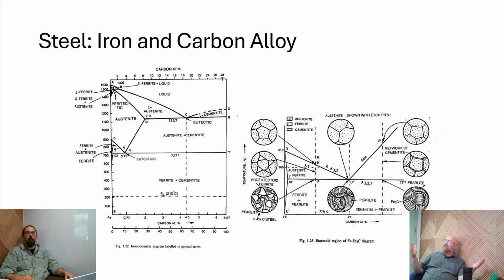Hydrogen explodes in the presence of oxygen, but we reduced the oxygen there. The only thing that was keeping the oxygen out of that superheated hydrogen was the Inconel retort. So we had to paint a ceramic coating on the outside of this crucible, but that eventually started ablating away, and so we were constantly reapplying it, and it was just a terror.